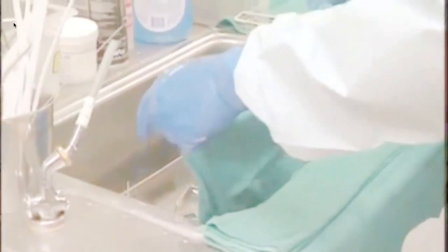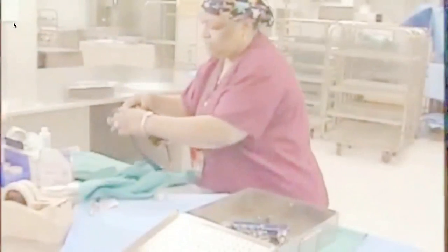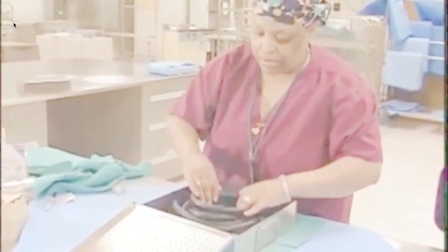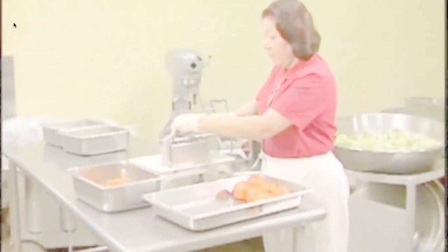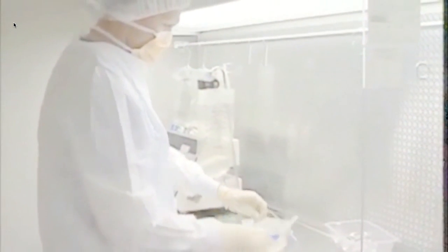Remember to consider areas that provide support for patient care. If these areas become contaminated from construction activity, the products or materials produced and distributed by these areas could transmit microorganisms to patients. Therefore, areas such as sterile processing, food preparation, central supply, and pharmacy will require similar assessments and protection from dirt and dust.